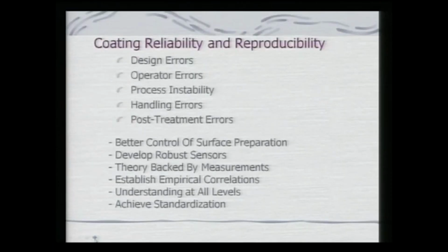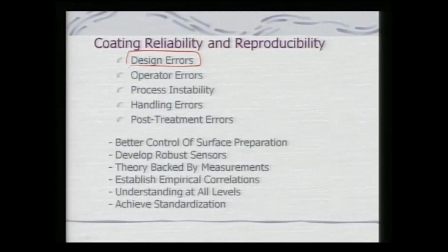Again, the reproducibility and reliability of the coatings is also an essential component in designing biomaterials, because if you want to create a coating, it needs to be what we intend it to be. But there are all these factors such as the cooling rate, the microstructure, even the parameters of the gun. So, we have to play a lot with them in order to understand and model it, and to understand it better we need to create some sort of process map to see where we can fit in our coating requirements and where we can choose the parameters from.